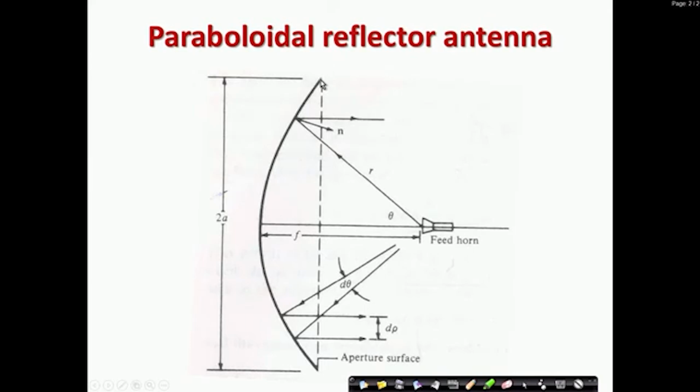So, in reflector terms people call it a taper in the amplitude. Now, this is not desirable, rather the other thing is desirable. We want to have P rho phi constant.